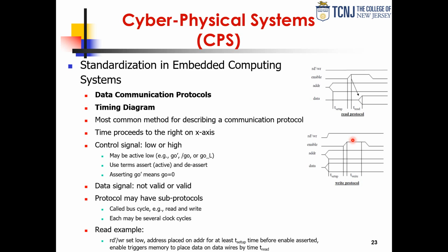So at that point we assert the enable signal. There is some time that goes by that is specified by design and construction and manufacturing of that component. And after that, we are guaranteed that the data has been written into that memory location. So at that point, we can deassert the enable signal and the transaction is complete.